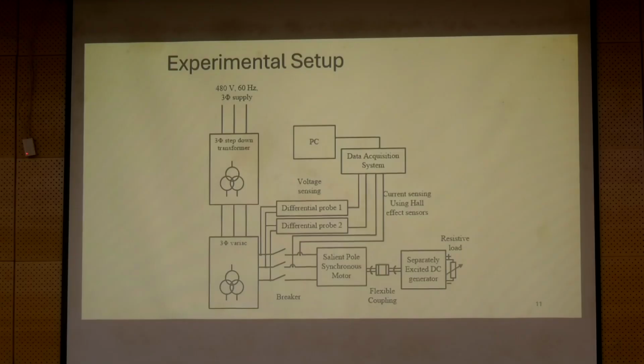So I placed the two current probes in opposite orientations. So when I acquired the signal, the line currents were not displaced by 120 electrical degrees. When I visualized it, I realized that something was not correct. Then I checked. Of course, once I knew what problem I had made, I didn't have to repeat the experiment. I just inverted one of the signals in software. But what I'm trying to say is there are many sources of error in data acquisition that you might end up making. Okay.